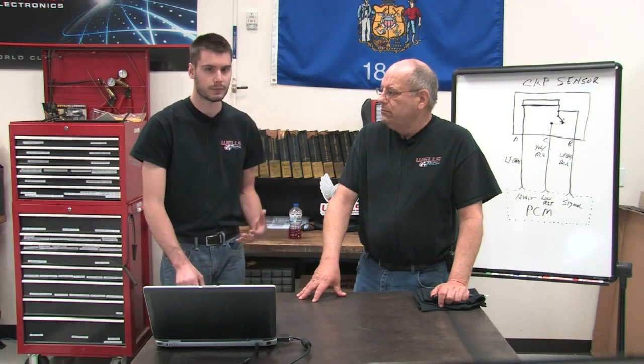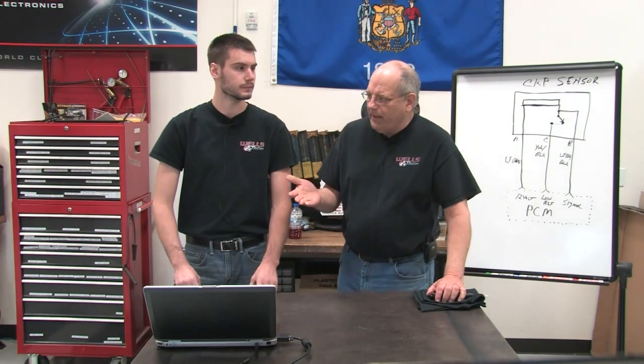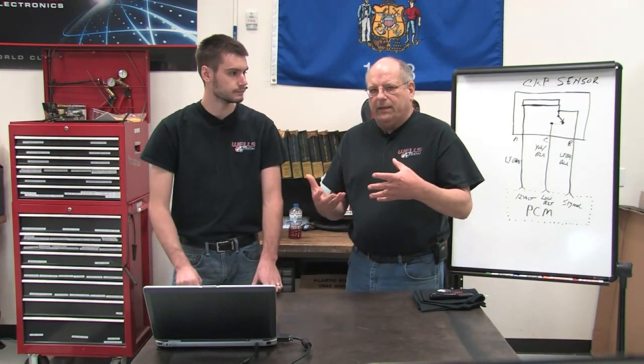But nobody says what exactly it's doing. From the most information I could find, they were saying that the relearn is taking those 24 pulses and making sure they're all evenly spaced and verifying there's no manufacturing flaws or defects or discrepancies in those 24 pulses. If they're not evenly spaced, if you have some that are tighter than others, that would indicate that you have a misfire.